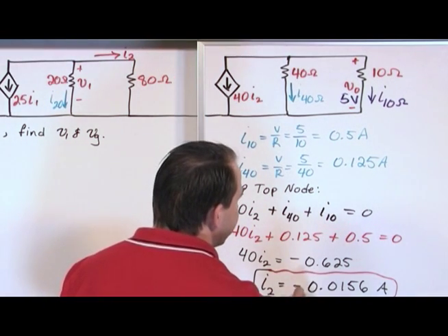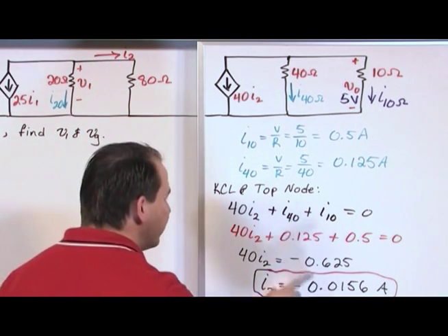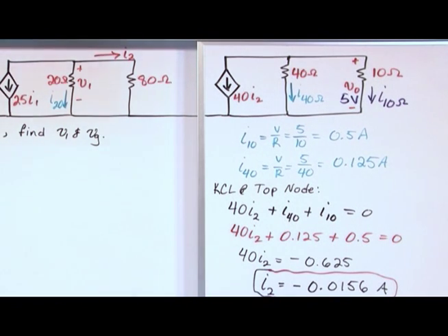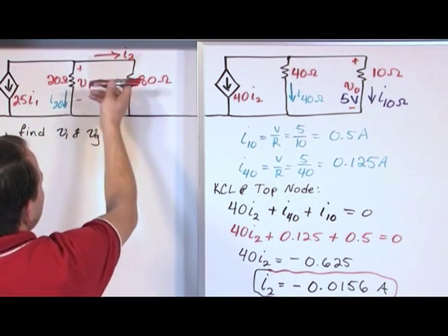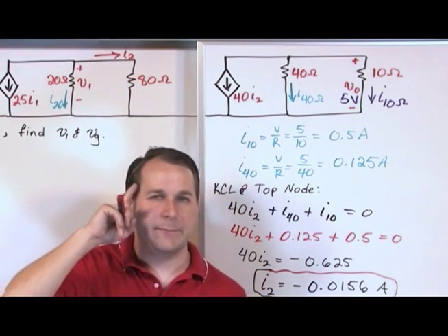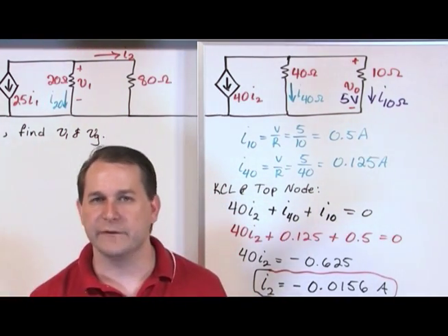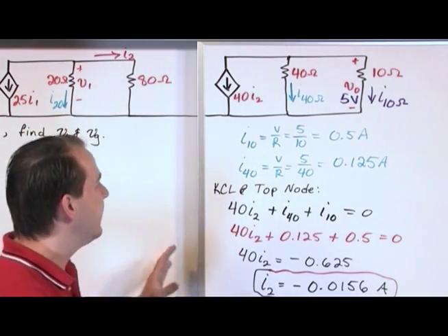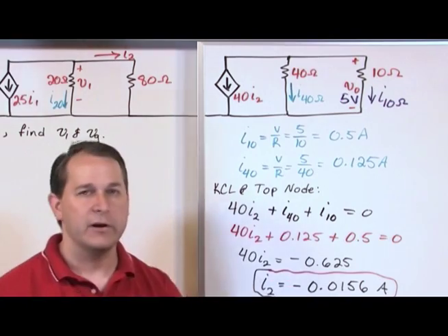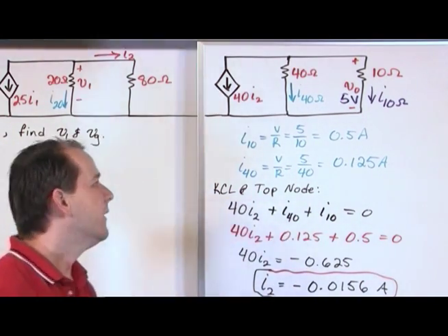So this value of the current is negative. Now what does this really mean? We've talked about this. If you get negative currents, it just means that the direction that you've drawn everything is really backwards. So if you really construct this circuit, I sub 2 is not really going this way. I sub 2 is really flipped around the other way. But that's just something we keep up here. We don't modify our drawings. We don't go up here and try to flip the direction of the arrow because that would be disaster. We've already written equations assuming that the directions are like this. We get negative numbers. It just means that we were backwards on the way we drew it. It doesn't mean we have to go change our drawing there.